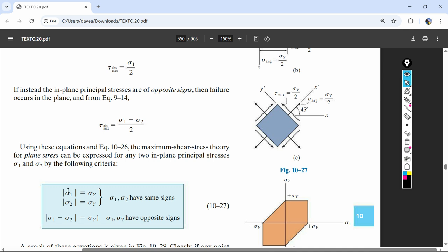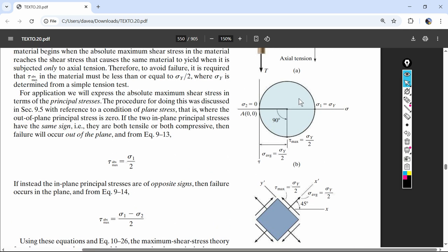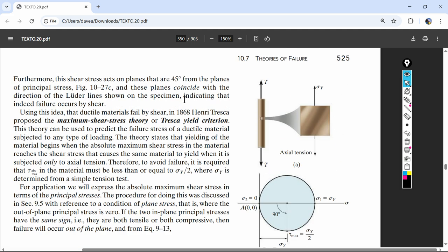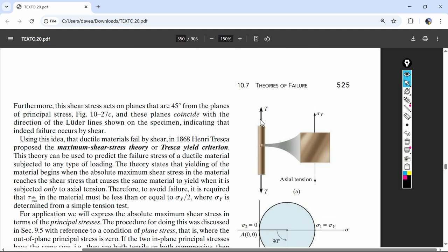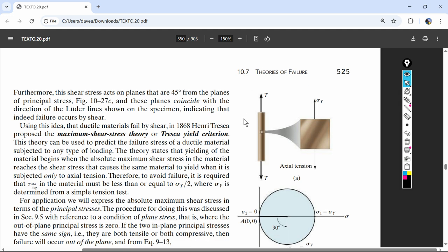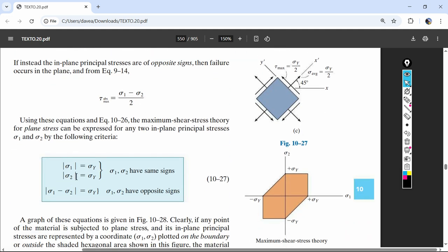I wish they just explained it as either or, because we just went over the scenario where, if these are both negative, then principal stress number 2 is the one that's most negative, and that's going to be the biggest number in compression, and that number is going to be the same as if you're pulling the specimen in tension. Hence the absolute value.